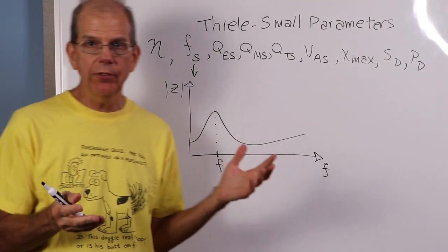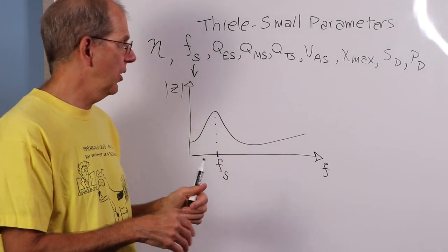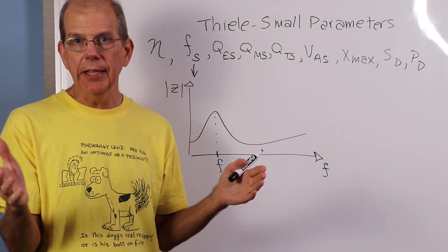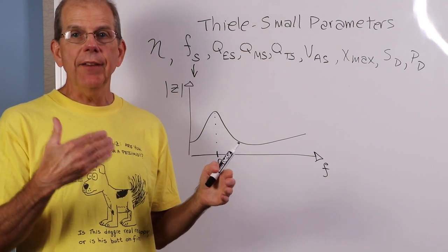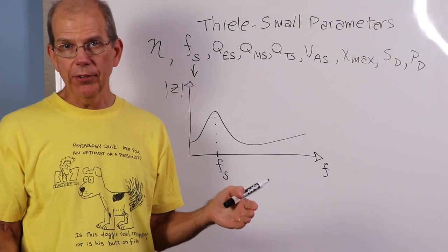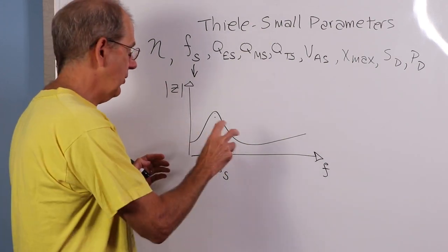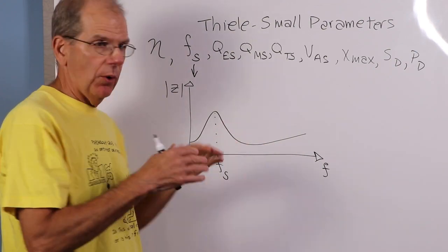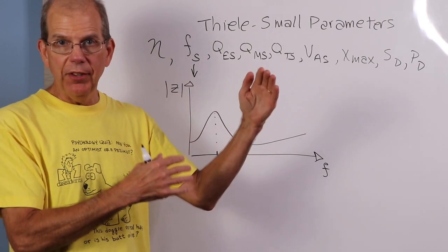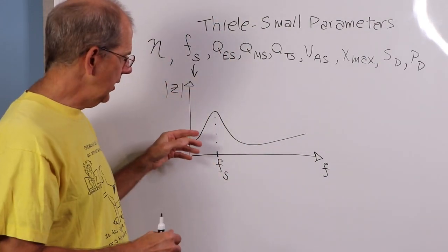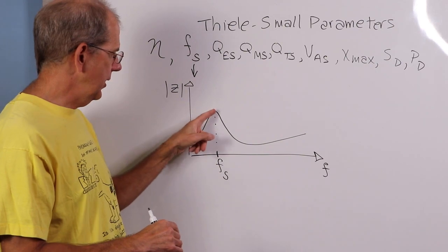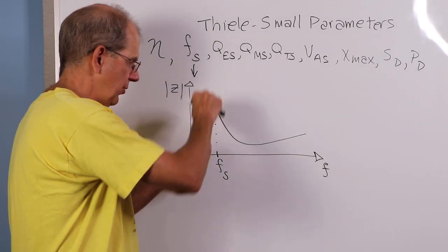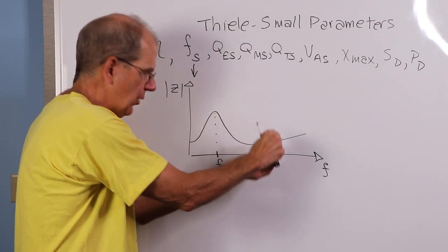You just get a voltage source, an AC generator, frequency generator. Put a large resistor in series with it, like maybe a 1k ohm, 10k ohm, somewhere in that range. That effectively turns the voltage source into a current source. And now, if you hook that up to the loudspeaker and you start sweeping the frequency around, you'll notice that the voltage goes up and down, right? The voltage across the loudspeaker goes up and down. And when it peaks, that will give you the Fs. So you're down here, you turn it up, the voltage will increase, and then hits the peak and drops back off, right?